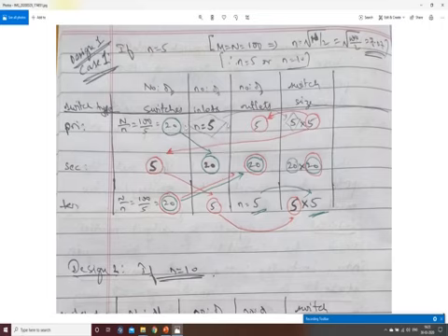Now what we generally do is make use of the standard switch size. That is, if I have a switch of 4 by 4, 5 by 5, 10 by 10, such switch sizes are specified as standard switch sizes. And if I have switch sizes such as 4 by 5 or 5 by 4 or any unequal numbers, then it turns out to be a non-standard form. So wherever possible we try to make use of standard switch sizes. So here let us consider that this switch size is 5 by 5 because there are 5 inlets. Let me assume that there are 5 outlets, so 5 by 5.